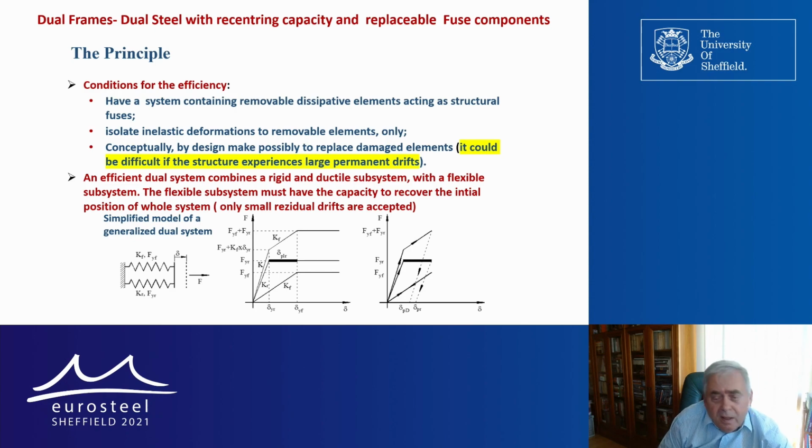When the earthquake has passed, we will have a tendency of the structure to recover the initial position. But for sure, due to the plastic deformation of the rigid one, only a small part will be possible to be recovered, and this will be the remaining residual deformation.